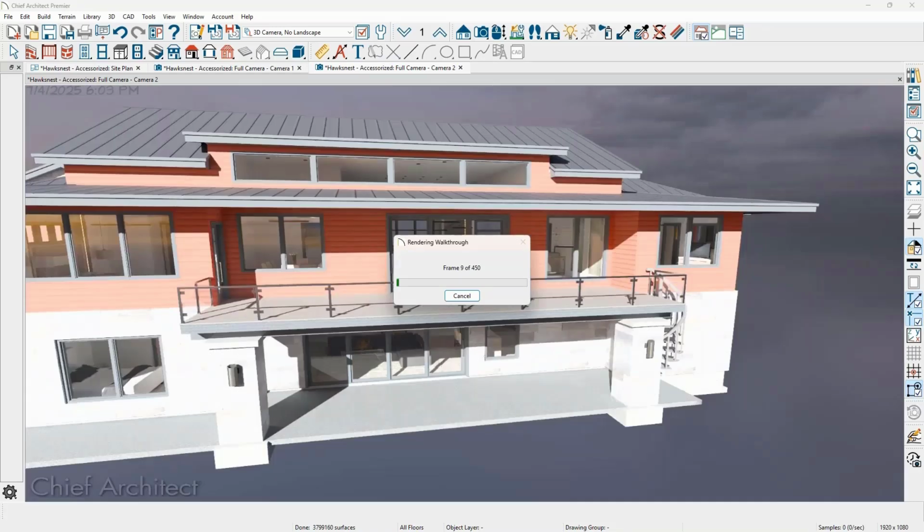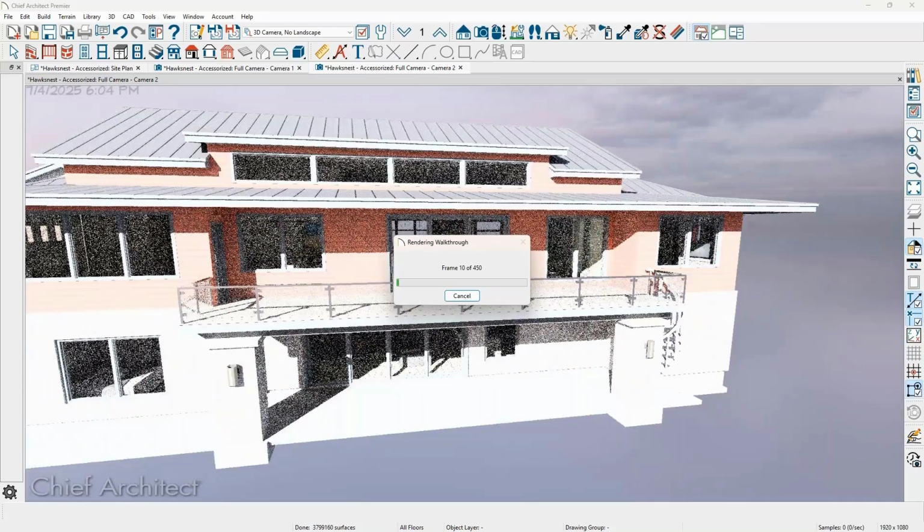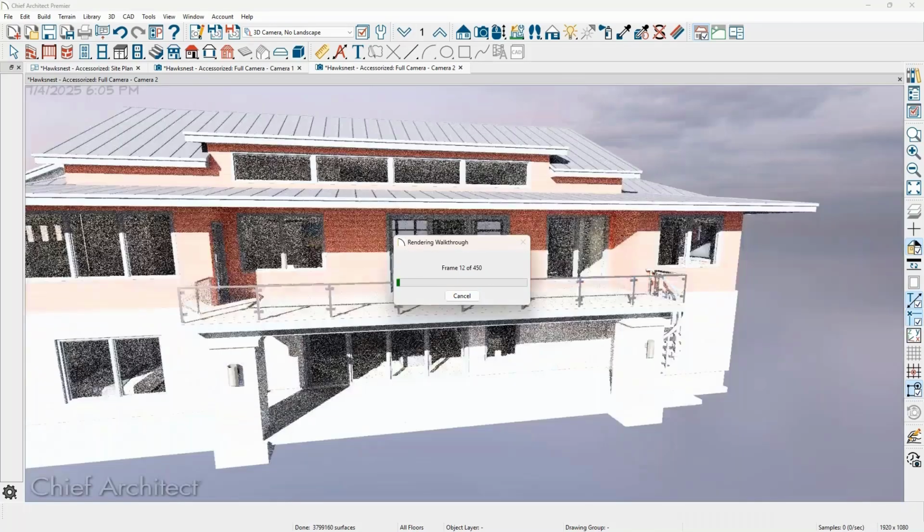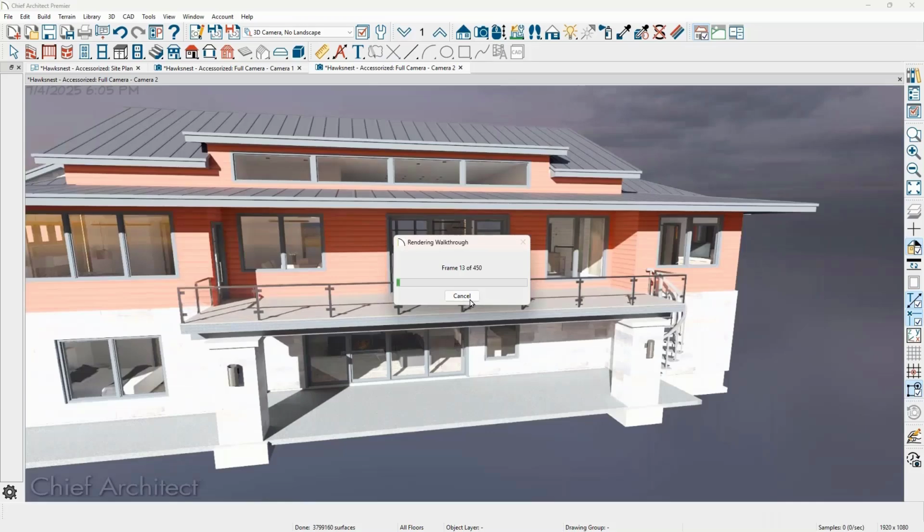Something that might help Sean there, it sounded like he might have been asking about being in a 3D view and just moving the sun, so animating the sun using the Move Sun tool. That can show you, in a static 3D view, the sun going from high in the sky to a sunset with the generated sky turned on.